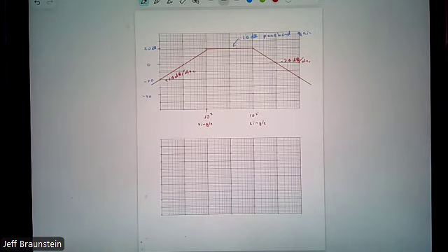Because our transfer function for the low pass is 1 over RC over S plus 1 over RC. So the denominator is S plus 1 over RC. There's our pole. Transfer function for high pass, S over S plus 1 over RC. Same denominator. Same pole, but because the numerator is different, it's a different filter. And for inductor and resistor, it's R over L.